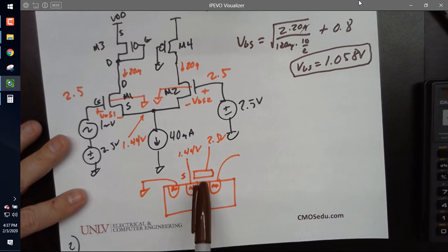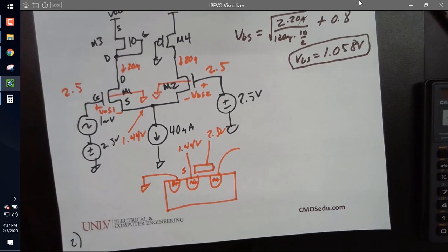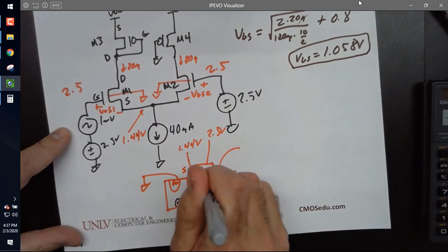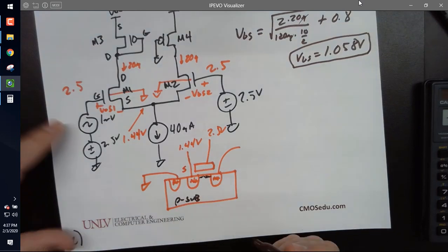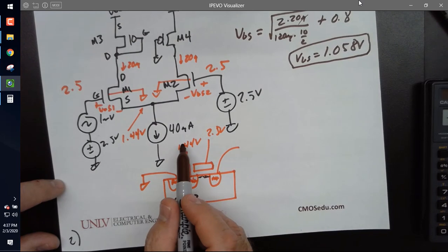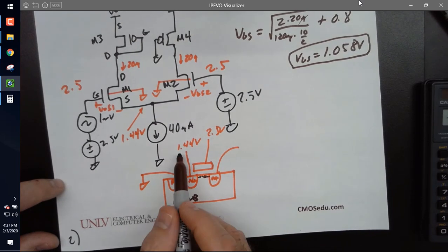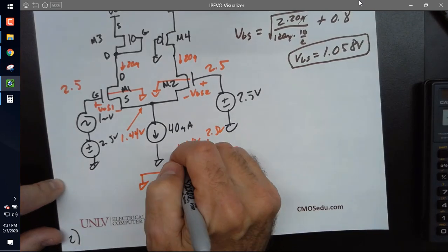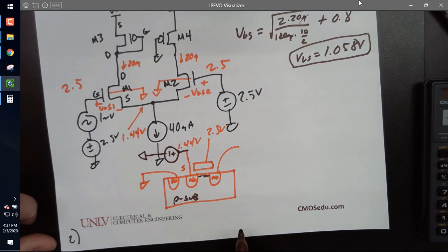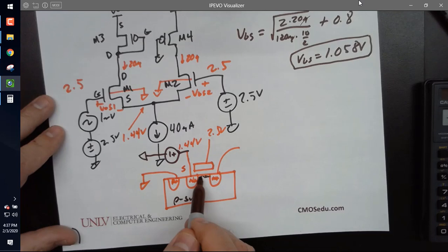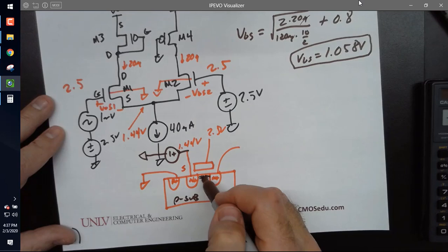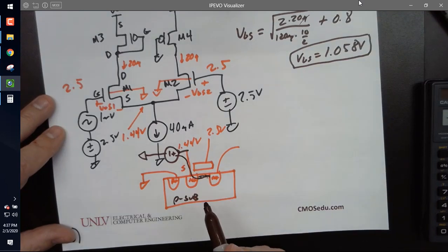So I'm going to ask some simple questions, so don't turn your brain off. When I apply a positive voltage here, what do I attract underneath the gate? I've got electrons, right? Does everybody see that? However, the body's at ground, and my source isn't at ground, it's at a higher, positive potential. Let's draw that on here. That source is sitting there, and I've got these channel electrons in there, and it says, hey, I see a positive charge. I'm going to steal some of those electrons over here. So it steals the electrons.